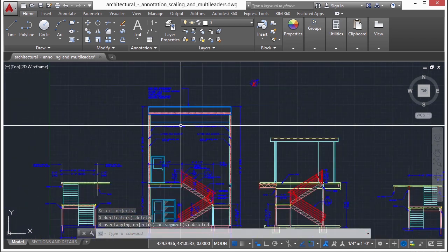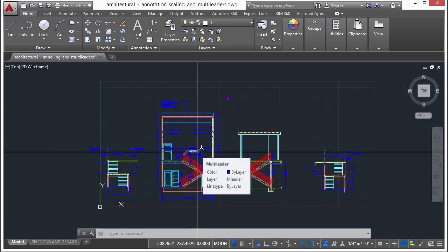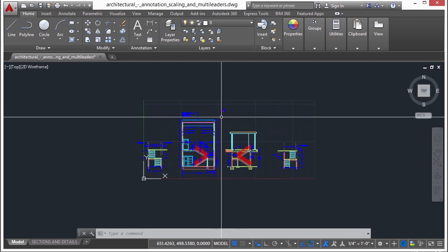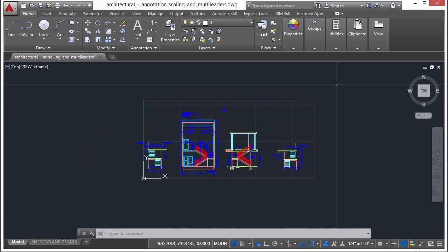So the overkill command, or the delete duplicates, is something that you're going to want to do after you've already done a lot of work in your file. Or once your file is complete, maybe you're sending it to someone, you can use the delete duplicate. You can actually select just a small portion as I did here, or you can select the entire file if you'd like. So this isn't something that you're going to use all the time, but I did want to show it to you